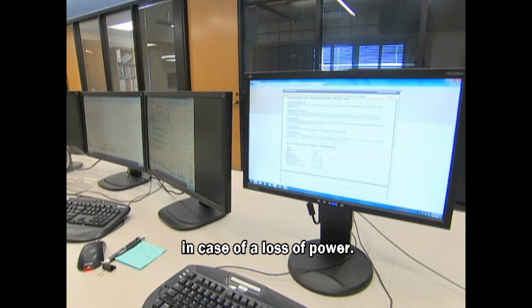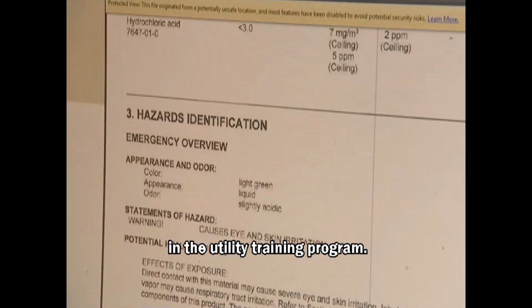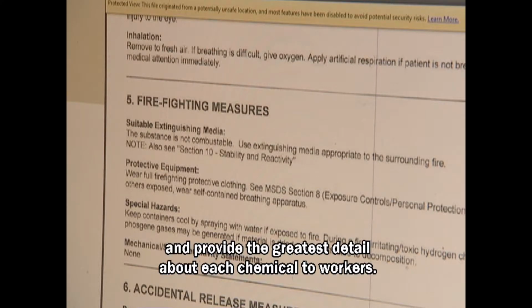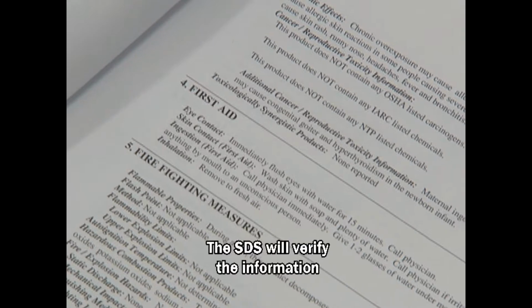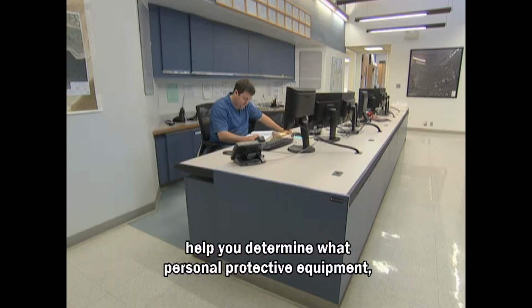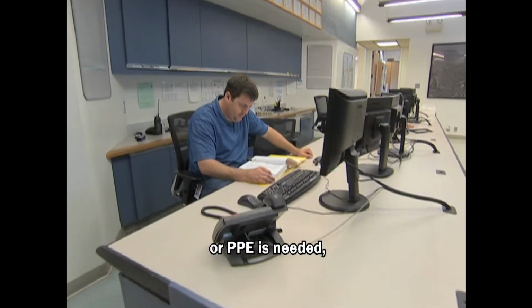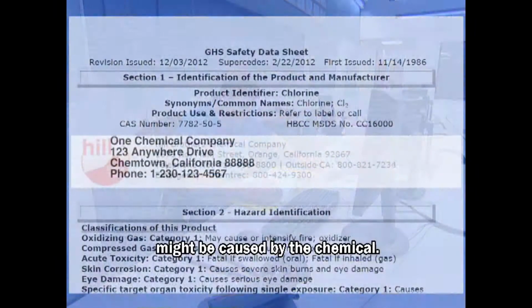The location of the SDSs should be covered in the utility training program. These documents are the primary source and provide the greatest detail about each chemical to workers. The SDS will verify the information on the chemical label, help you determine what personal protective equipment or PPE is needed, and tell you if symptoms you may be experiencing might be caused by the chemical.